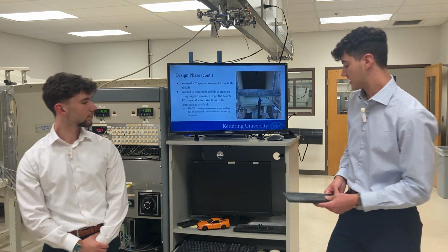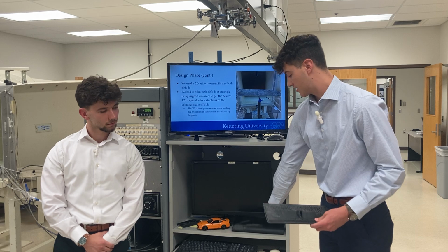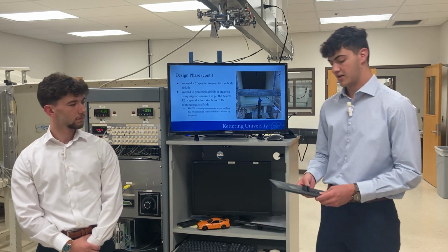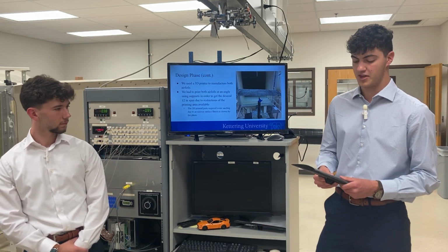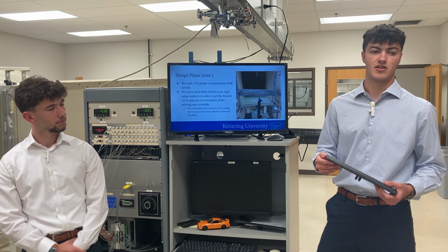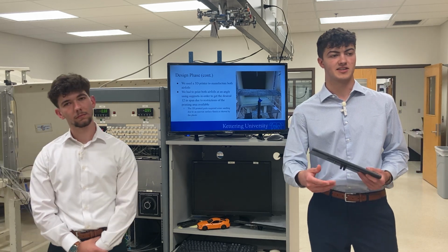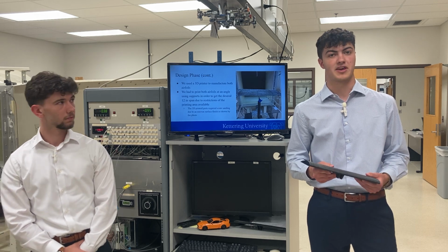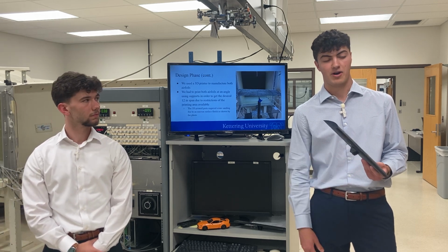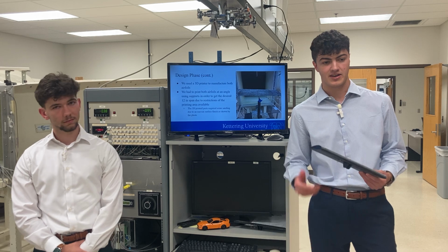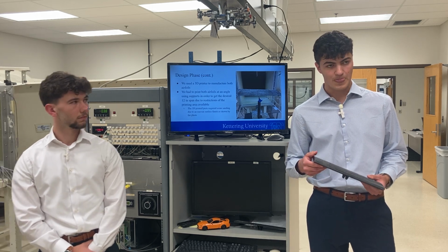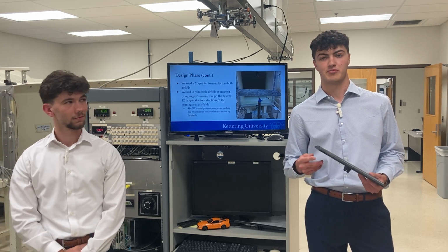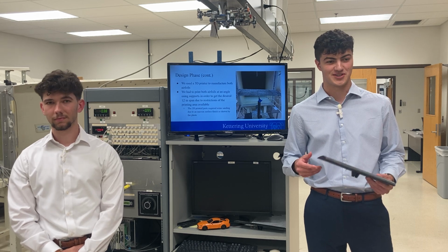But moving on, like I said, the 3D printing, one flaw that we encountered while doing it was the base of our 3D printer was only 10 inches by 10 inches by 10 inches high. So we ended up having to print our 12-inch span wings at a hypotenuse 45-degree angle on the bed using supports. While printing, we incurred 2 failed prints, which set us back and was very frustrating.